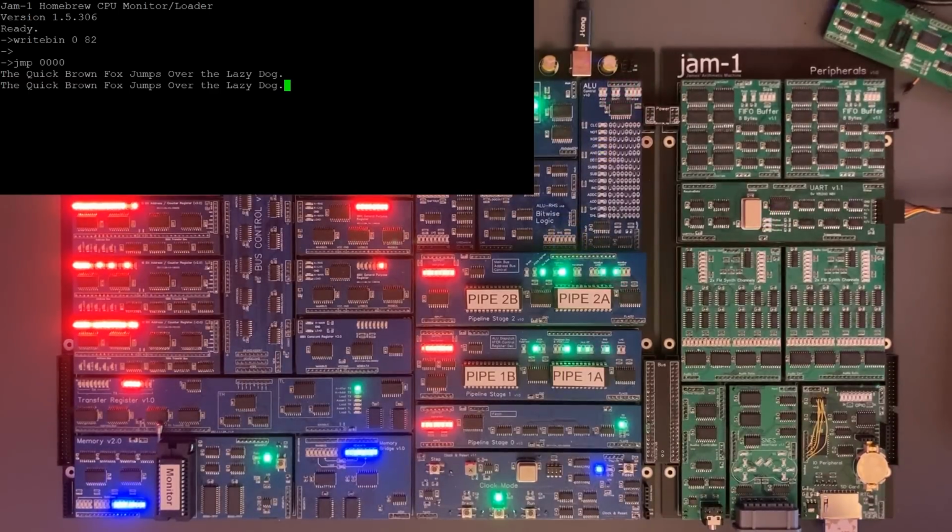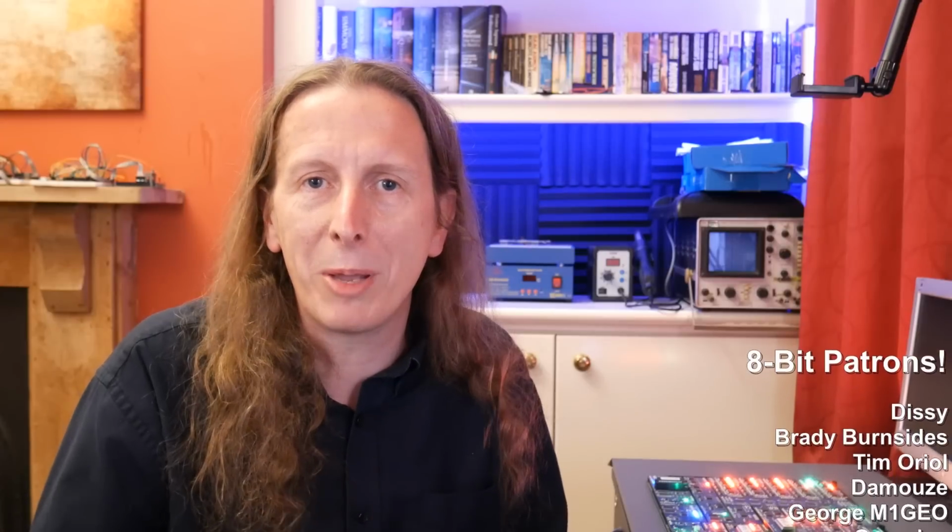Don't think there's much else to do here. What can I say? We've achieved everything we set out to do. We've fixed the baud rate issue on the silk screen, we've got the clock output, and we've got the hardware flow control, or at least the ready to receive section of it. That's going to give us an awful lot of interesting functionality for the system when we're running in the slow clock speed interactive mode.